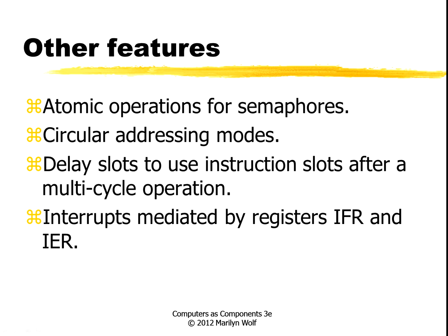The architecture provides several other features. It provides atomic operations for semaphores, some circular addressing modes, delay slot operation for performance optimization, and the interrupts are mediated by 2 registers, IFR and IER.